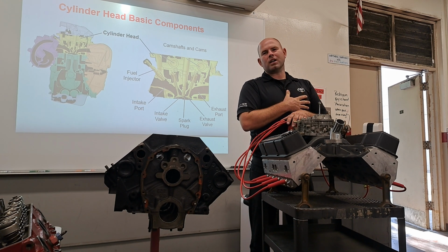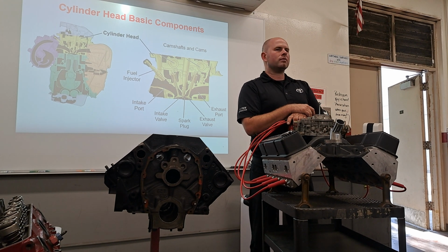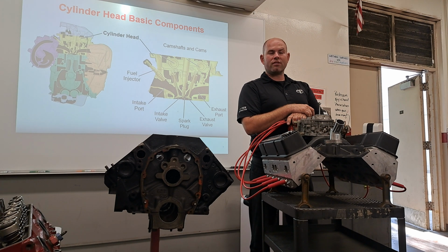I tell you, I'm sorry, I just don't. I got fuel injected stuff. I got carbureted stuff. Fuel injected, if you get it dialed in, is to me just superior. Carbureted stuff is easier because you need your pocket screwdriver and that's it. You don't need any laptop, tuning software, or scan tool. But carburetors just tend to always need a little love.